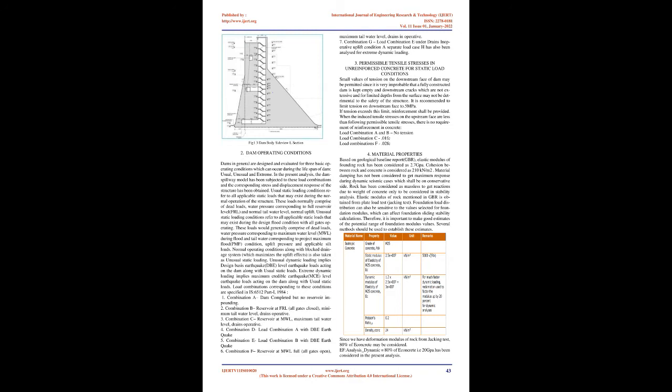Usual static loading conditions refer to all applicable static loads that may exist during the normal operation of the structure. These loads normally comprise dead loads, water pressure corresponding to full reservoir level, FRL, and normal tail water level, normal uplift. Unusual static loading conditions refer to all applicable static loads that may exist during the design flood condition